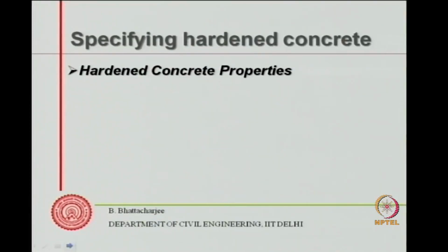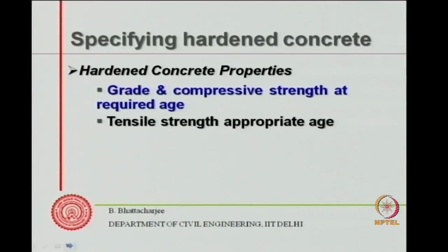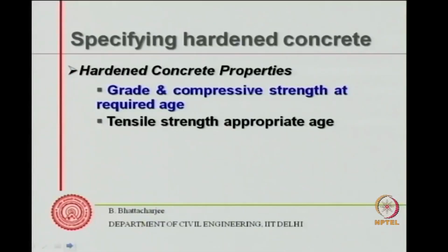Hardened concrete. Since concrete is a structural material, we specify the grade of concrete in terms of its compressive strength at a certain age, because in module 1 we have seen that the reaction of cement with water produces a material which is stone-like, but the formation of this hardened material from a plastic state takes time.